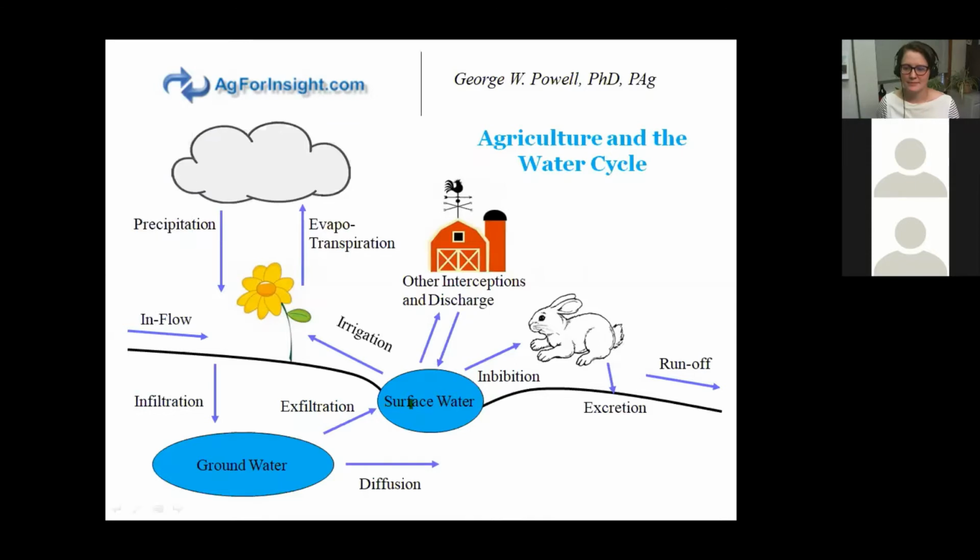So the water cycle. Most of the planet is covered in water, about 70% plus. And as that water is heated by the sun, it is pulled up into the atmosphere through a process of evaporation and transpiration. Transpiration is essentially water that moves through plants first before it enters into the atmosphere. When it gets up into the upper atmosphere, it cools and then returns back to the earth as precipitation. Comes down as rain, comes down as snow, as ice pellets. In a month or 2, you might get all 3 of those at the same time. But that's the major input of precipitation to most areas.